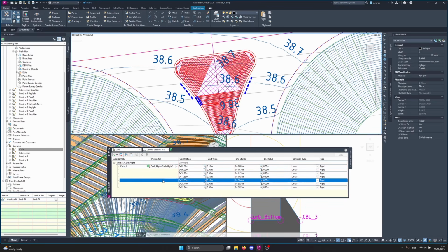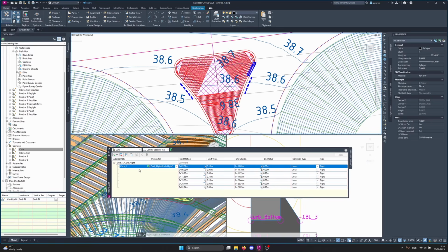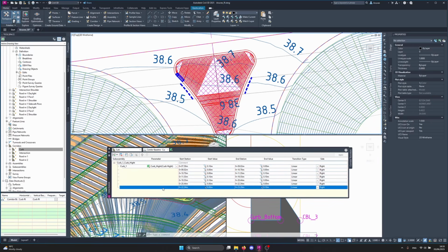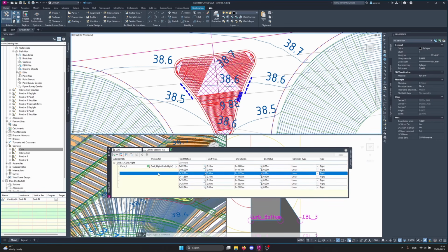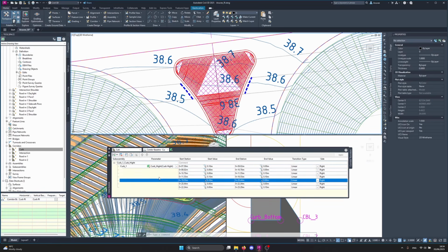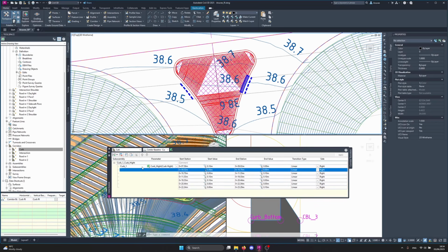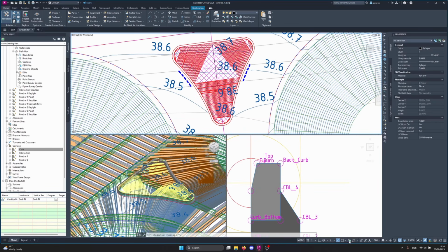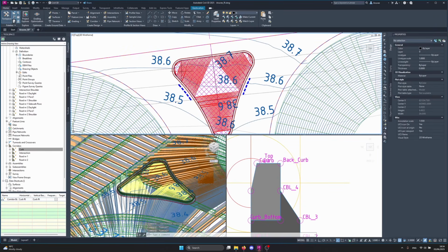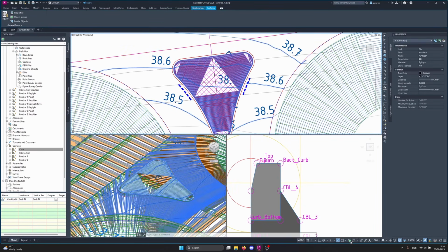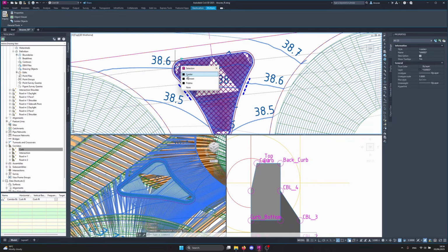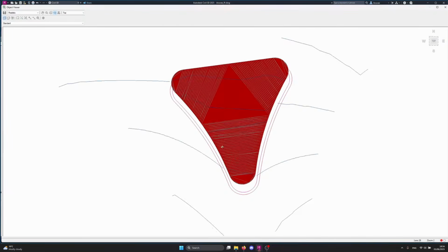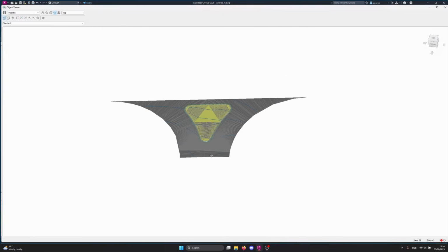And just with the corridor transition and with the height parameter, you could very easily manipulate the surface and the curb height of this pedestrian island. So that's a cool feature to have. And yeah, that's about it. You have this surface, you have this corridor with the curb, and simply as that you have a pedestrian island.